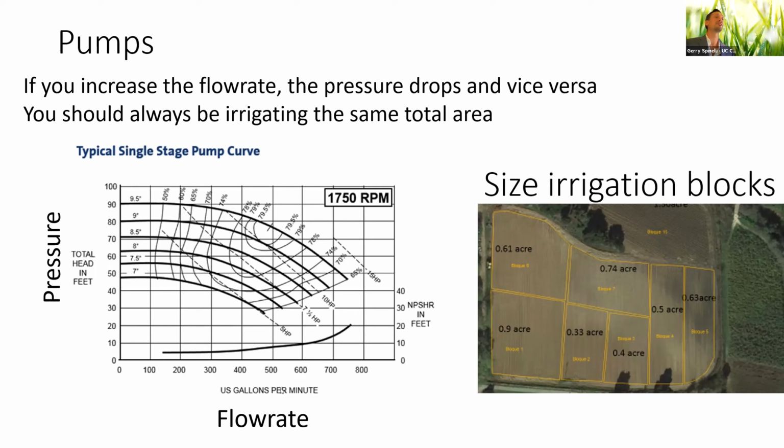Or in terms of an irrigation system, you can say, okay, my irrigation system has 100 sprinkler heads per acre, and each of them takes 3 gallons per minute. Therefore, when I open my irrigation block, I have 300 gallons per minute. All this flow of water is going into my irrigation system through my main line.